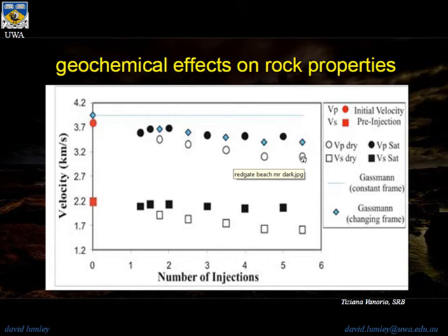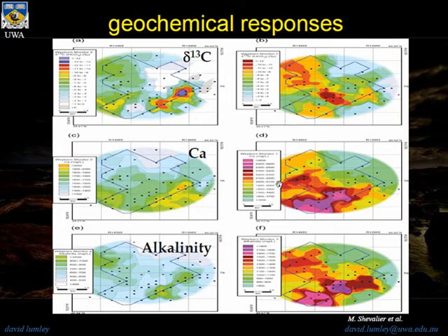Last couple of things as I wrap up here is passive microseismic, and I know there's a lot of interesting work going on up here, but here we are, passively recording, listening to microearthquakes, which do occur during CO2 injection in some reservoirs. Here's a very interesting example conducted by Jim Rutledge at Los Alamos National Lab. The blue dots are microearthquakes located from a well during CO2 injection in an EOR project. These blue dots seem to be correlating with the front of CO2.